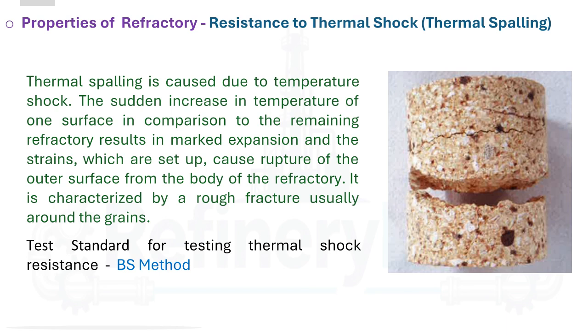The test continues until the specimen finally gives way, when it can be broken apart by hand. That moment marks the end of the test. The report records the test temperature, the number of heating and cooling cycles the specimen survived, and the exact cycle when cracks first appeared. In short, thermal shock testing tells us whether a refractory can survive the rapid temperature changes that are common in real furnace operations.